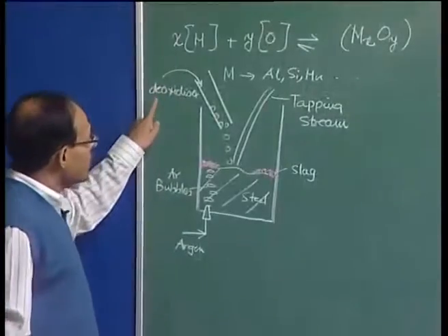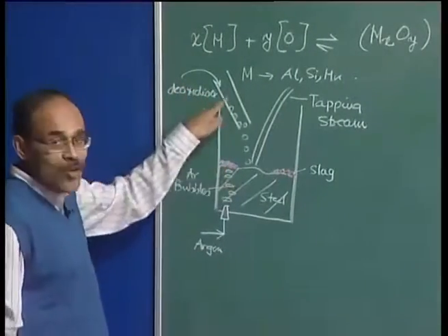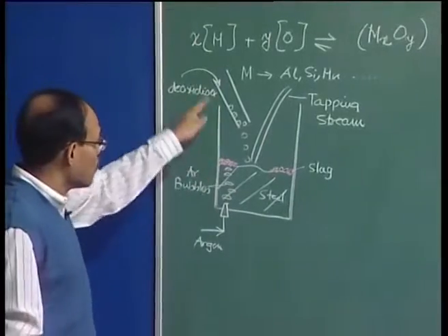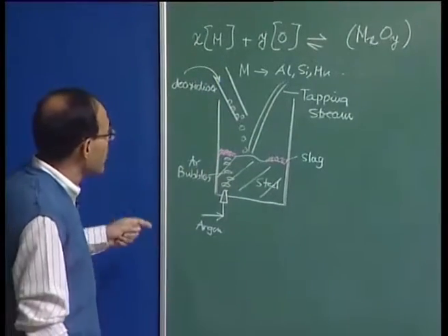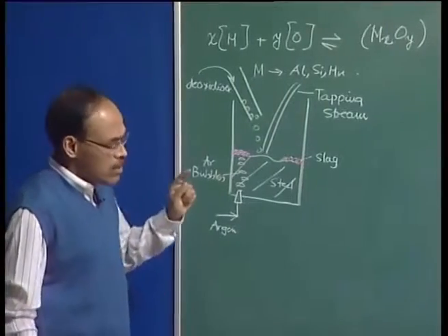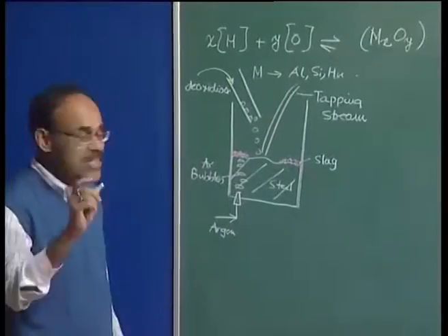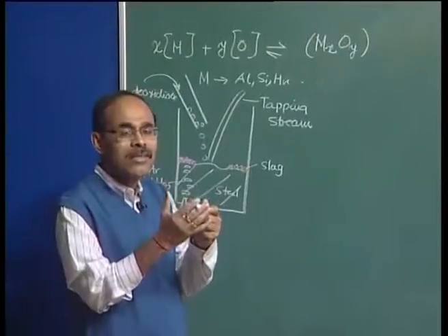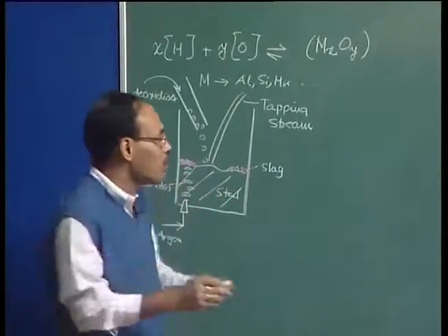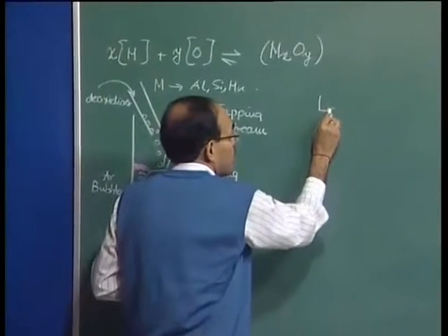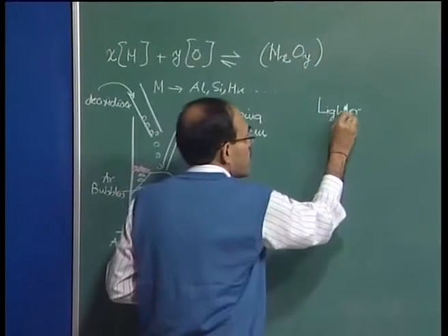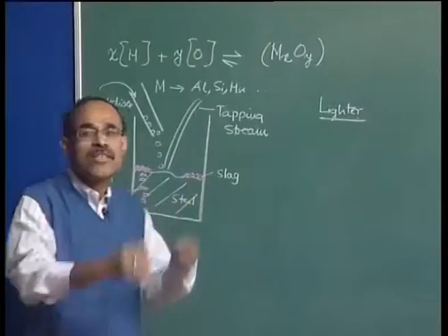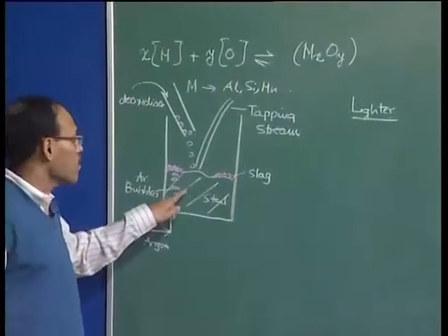Now this concerns the bulk addition of deoxidizer elements like aluminum, as we are talking about. And one property I think you should have been able to register by now is that these deoxidizer elements like ferrosilicon, silicomanganese, and aluminum are much lighter than steel. Their density is much lighter than the bulk steel.